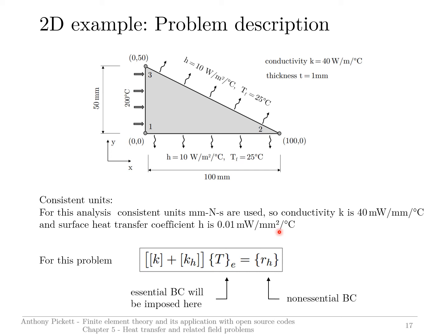Now there's one point perhaps I should explain a little better. I've used the terms transient and steady state several times during this presentation, and perhaps it's not quite clear what I mean by that to some of you. If we were to suddenly apply this 200 degrees at this particular point to this plate, and this plate had an initial temperature of 25 degrees, then it would take time for the heat to move from this point through to here.